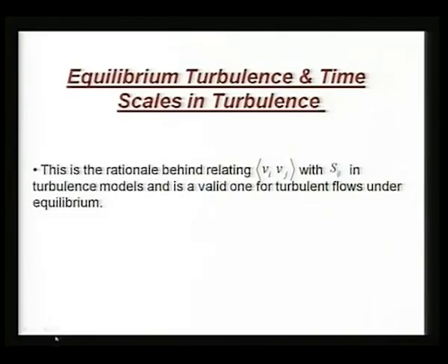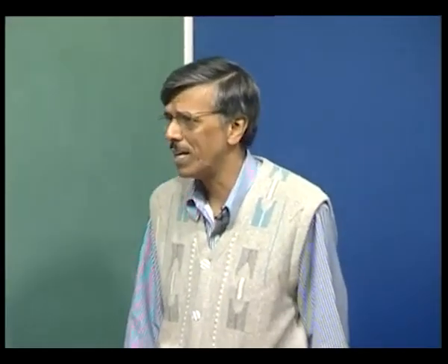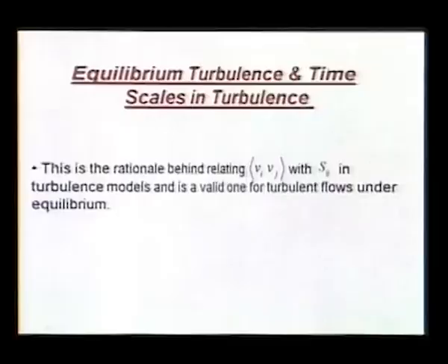So, this is also what is done in most of the algebraic or differential equation based turbulence models, where you eventually try to write out some kind of an algebraic relation or a differential equation which relates the evolution operator of this with the help of the mean strain rate. This is what you do in turbulence models.